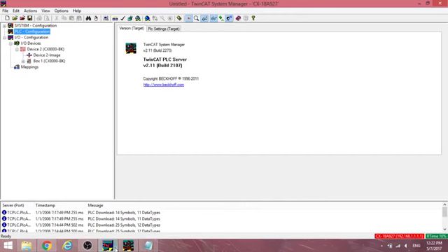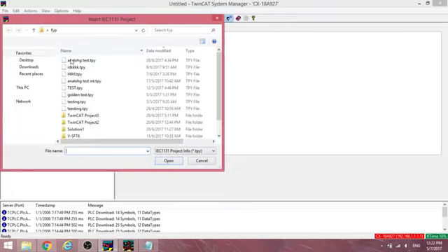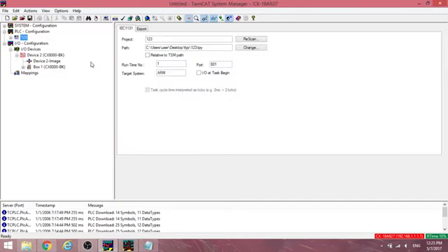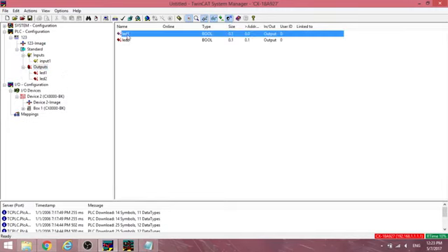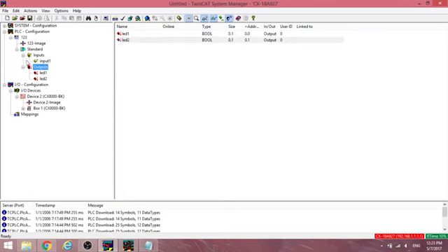change over to the System Manager, right-click on PLC Configuration and click Append PLC Project. Choose the TPY save file created earlier. Under Standard, go into Inputs and Outputs to ensure that the previously defined variables are present and allocated to an